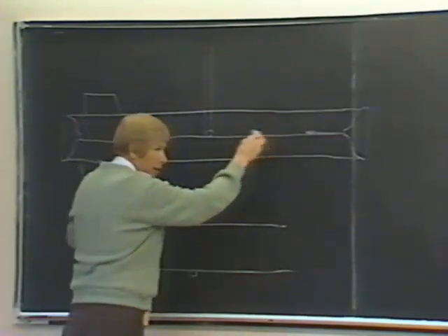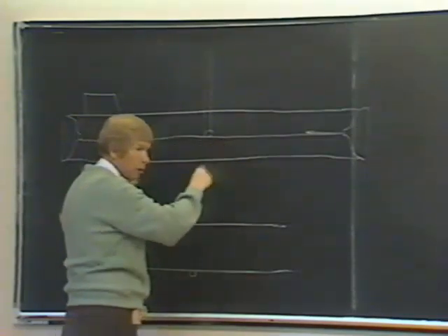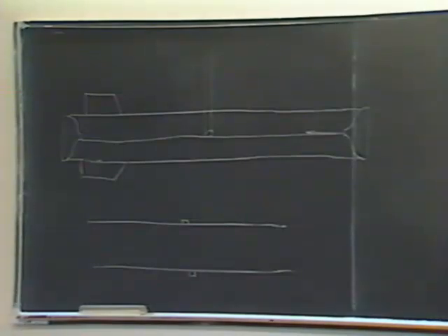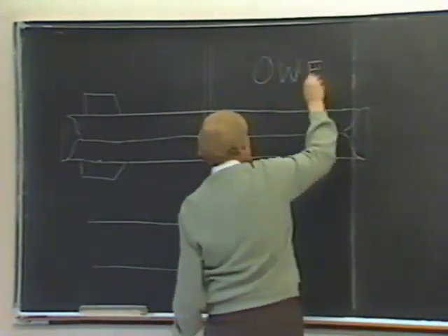You may have essentially a slurry, that is, material carried up into suspension, and if the concentration is very high, as in the Thames, for example, or the Gironde in France, or any number of estuaries where you have a large tidal range, you may have a slurry, and not much happens. That is, it's just transported back and forth with the tidal current, except near slack water.